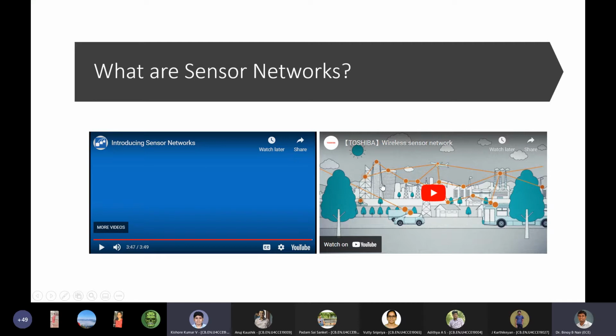No, you cannot. The length of wires is one major challenge because you have signal loss. When the sensor reads some data and it needs to be transmitted, the output you're getting will be of the order of a few millivolts, or at the most a few volts. And in an industrial scenario, the longer the wires you have, the more risk of electromagnetic interference comes in. So the best option is to have short cable lengths, and once it reaches some kind of controller, you convert that into completely digital form, and once it is in digital form, the risk of corruption becomes less.